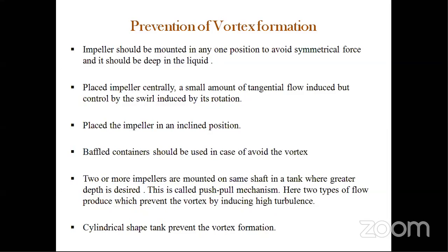So when baffles are present, a vortex formation may occur, but it is quickly dissolved in the liquid. The vortex does not continue for very long. So if a vortex is present in your container or tank, you can prevent the vortex formation in this way.